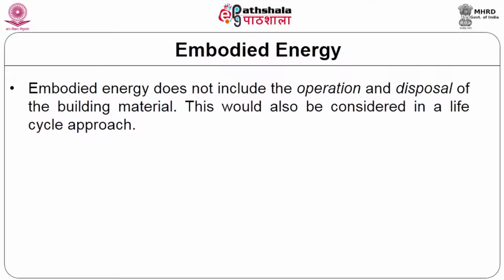There is a lot of confusion within this, that embodied energy includes operational and disposal of the building. It is wrong. It does not include operational or disposal of building energy. This would also be considered as a life cycle. This could be used in a life cycle analysis of the entire building material life, but it is not the embodied energy of the material. Embodied energy is just the upstream process till it reaches the site.